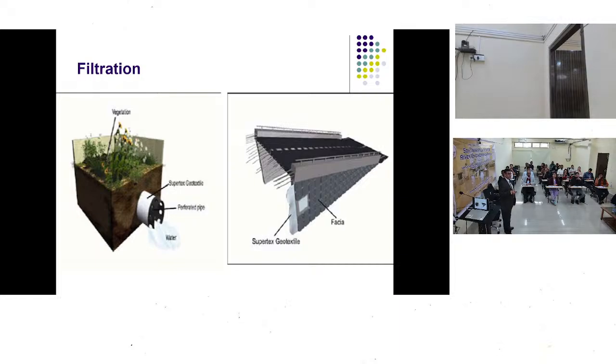Now, the basic problem at times in big fields is that through the weep holes, soil particles also start coming out, and you want to restrict the soil particles. So what we do is we can install a non-woven type of geotextile over a perforated pipe. I wrap my perforated pipe with a non-woven geotextile and have it installed in the weep hole. So what will happen? It will not allow the soil particles to move, but will allow the water to move out.